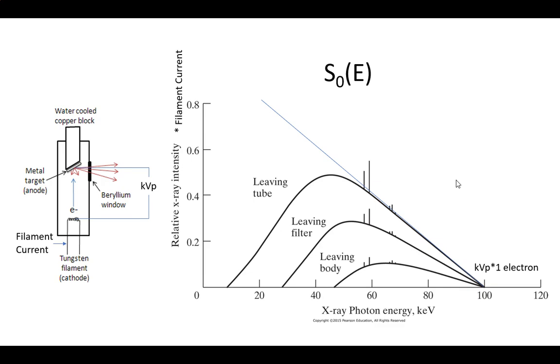If the electron comes out, that means those electrons jump out and they're kind of hovering in and around the filament. If I took the temperature and I raised it, guess what happens? I raise it above that level, I'm going to start promoting electrons like crazy. Right? So we call these thermionic electrons. Right? Just think thermal. They're thermally produced electrons. And this is a byproduct of something just being a good conductor, and metals are good conductors. That's why we use a metal filament there, tungsten.